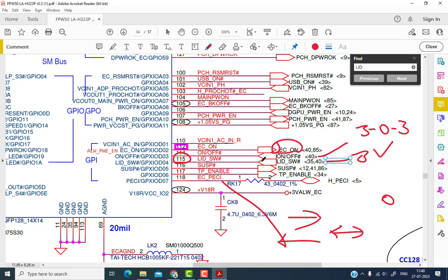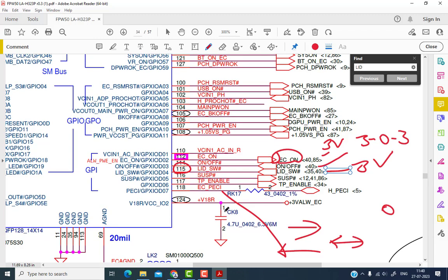So you have to check that. Okay, so you have to check the signal, that is a 3 volt is here. Okay, and then the 3 volt and 5 volt buck converter will start functioning, giving the power, and then SIO will generate the rest of the signals.